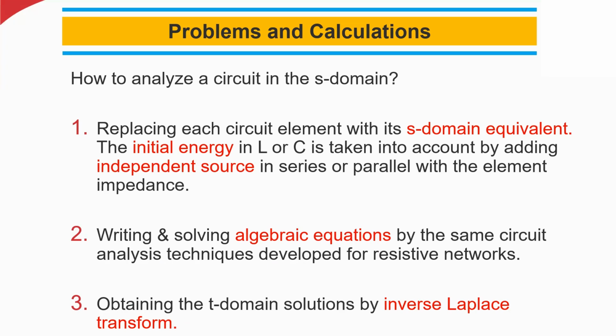So what does it mean? First you are converting the circuit into the S domain and writing the equations in the S domain, and of course you are performing the Laplace transforms. After you complete that, you have to convert back into the time domain, because once you perform the Laplace transform of these algebraic equations, it's in the S domain, the frequency domain. But we want the final answer to be in the time domain again. So for that you have to perform the inverse Laplace transform.